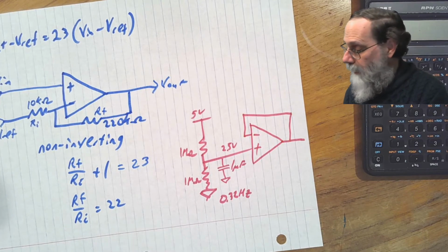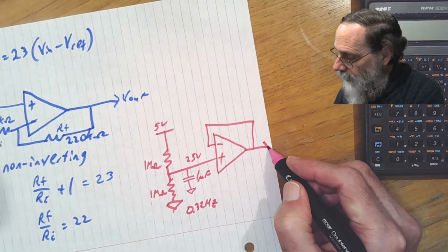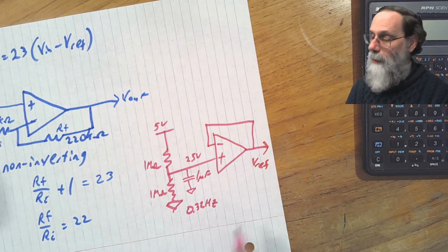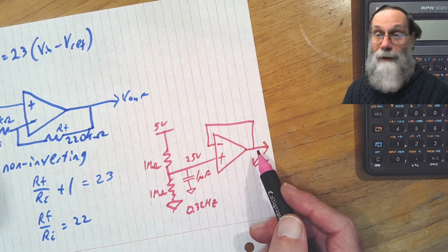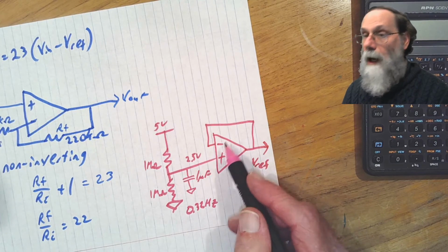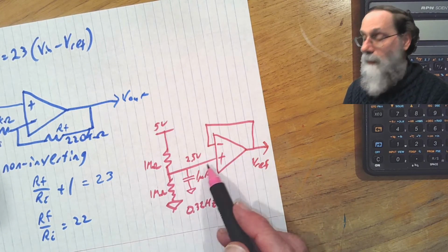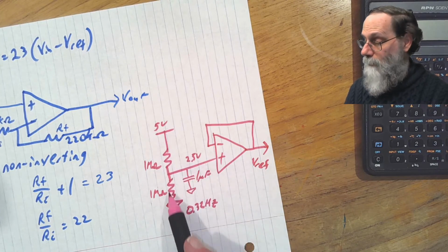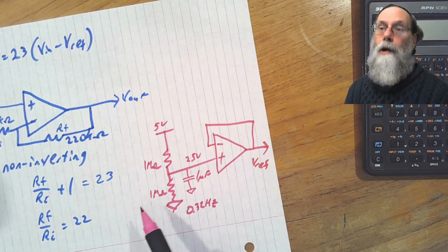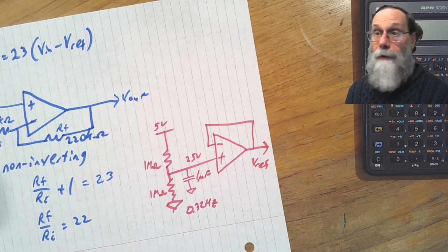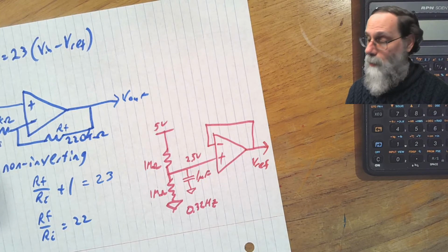And this is the way that we can generate VREF. We got a current here. We can have as much current as this op-amp is capable of delivering. And we have it at the constant voltage that we've selected with this low-pass filter from the power supply here. And this is a very standard sort of circuit. We'll be using this one over and over again in this course.